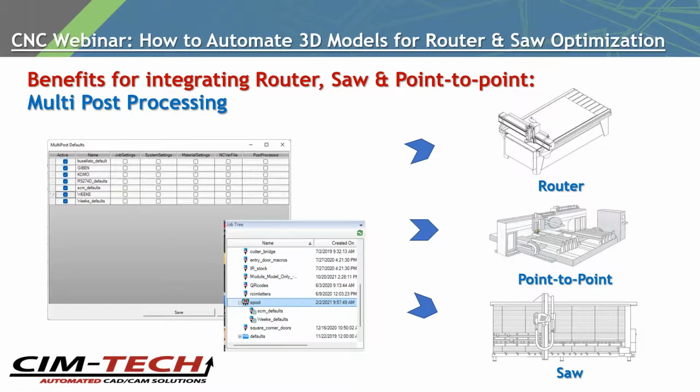So on one machine, it may be .txt, another one might be .mpr or .cnc, and just to give you some example of what job settings would be. And you can have a job that runs through 2, 3, 4, 5, however many machines as you want. And that one job will output the programs for multiple machines with our multi-post.